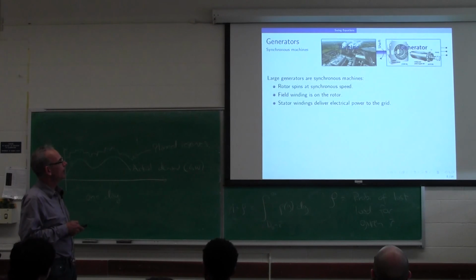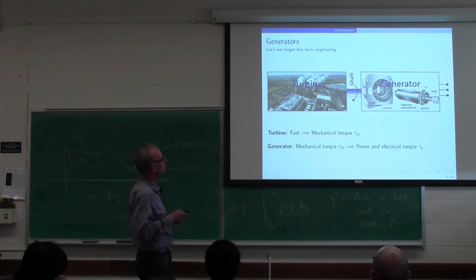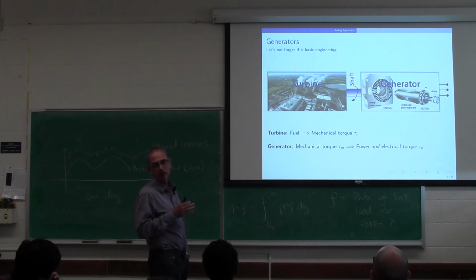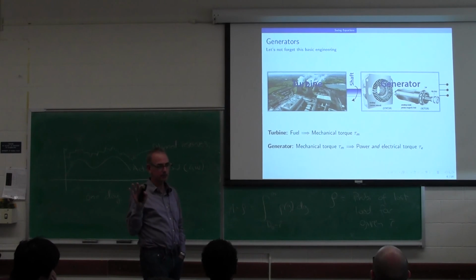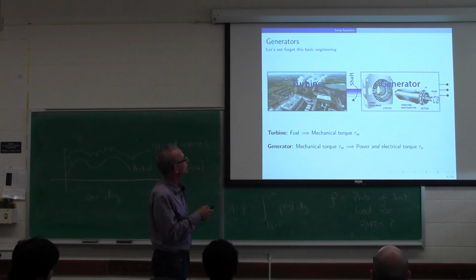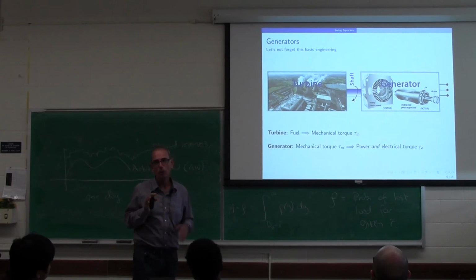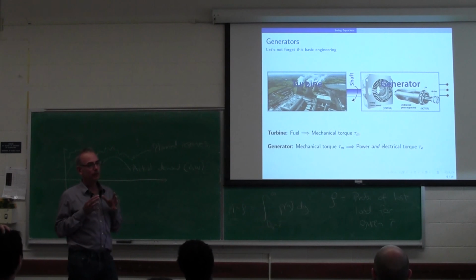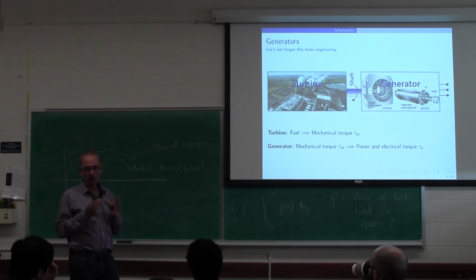And I want to say something right here. We're going to be talking about keeping the frequency at exactly 60 hertz. In the United States, we're going to be trying to keep the frequency within 59.95 or 60.05 hertz. Last year I taught this course, and I wanted to find one source that would tell me why.